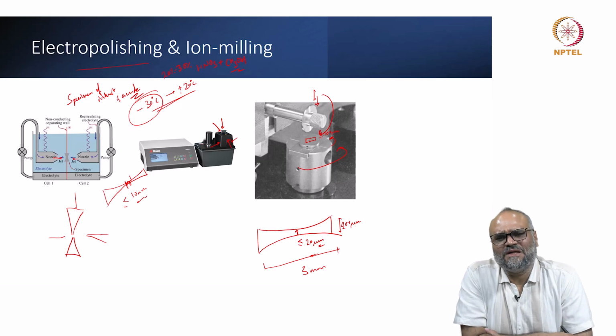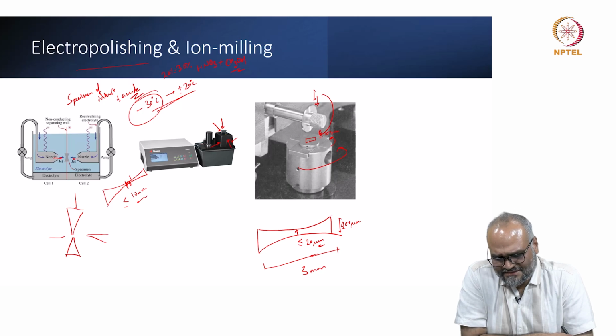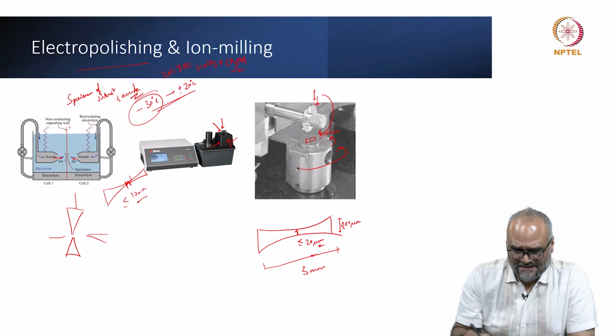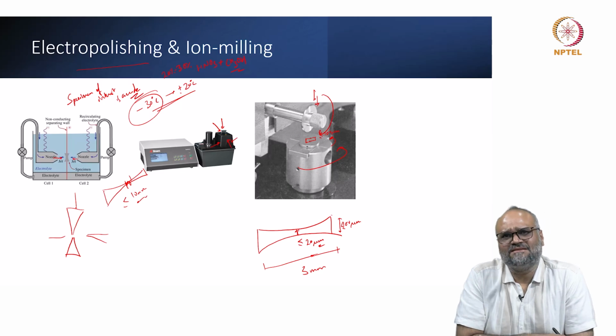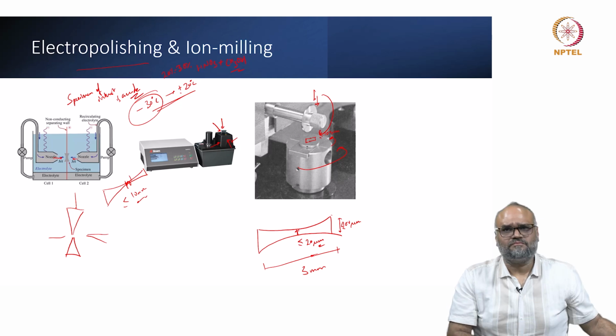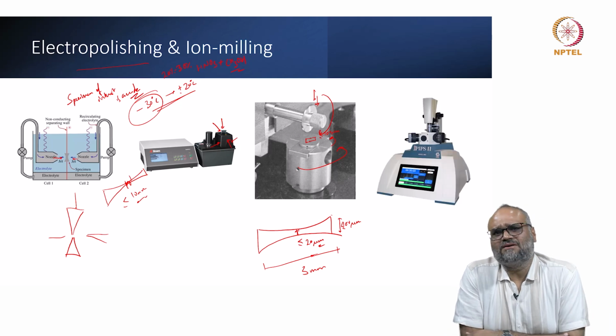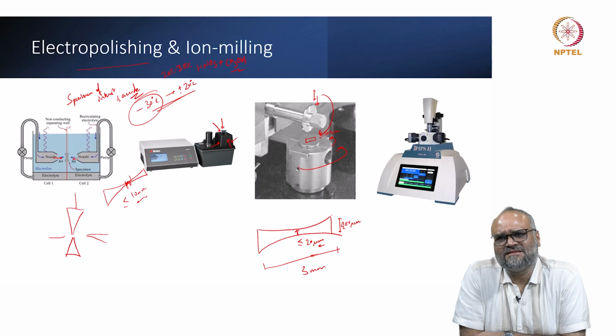Quite often a very bad practice is you do not check the thicknesses after you dimple, and this can have a severe detrimental effect on the ion milling systems you use. And moreover, the thinner your dimpled area is, the shorter the milling times are and the better quality specimens you get. So here is how a common ion milling system looks like.